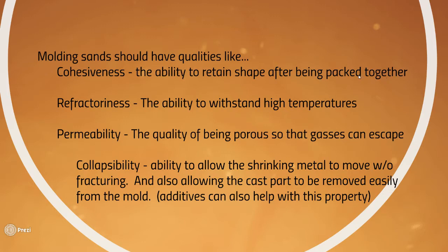If your mold is not strong, it will be falling apart, and then you're not going to have a very good part that solidifies. Refractoriness refers to how well this sand is able to withstand high temperature. So you'll hear that word a lot. Sometimes you'll hear refractoriness, which is the description of a quality. A lot of other times you hear refractory, which refers to materials that can withstand high temperatures.